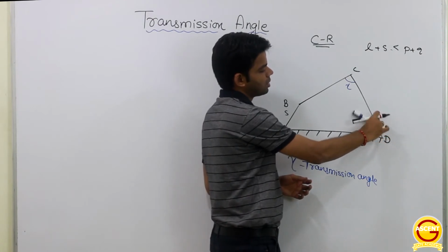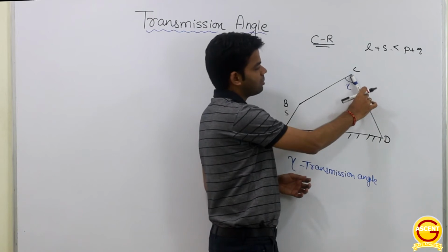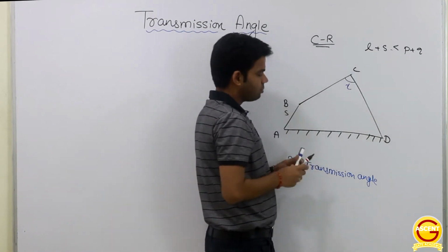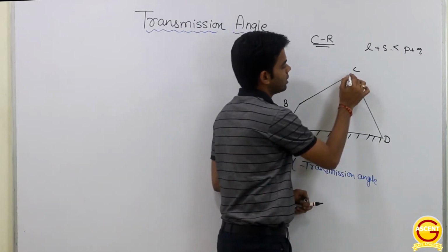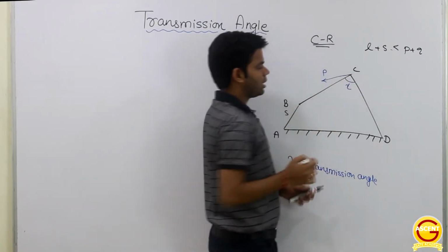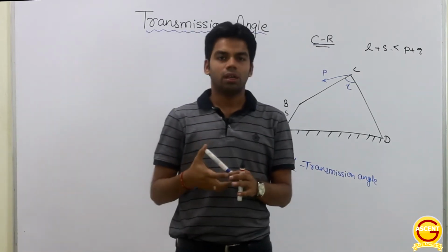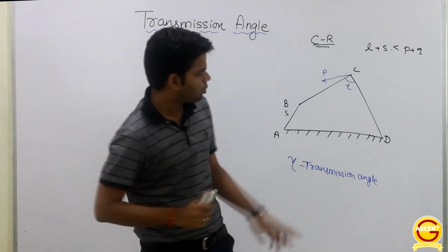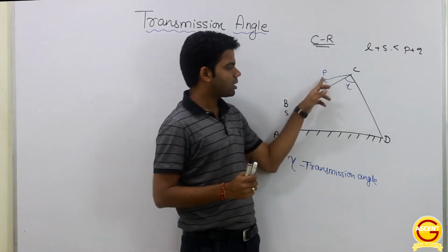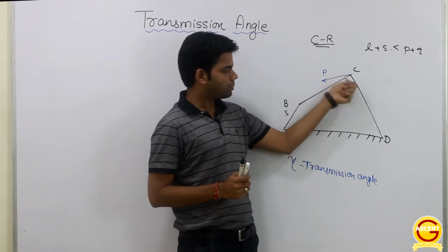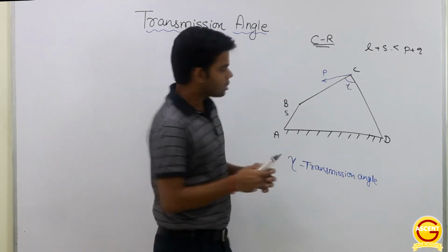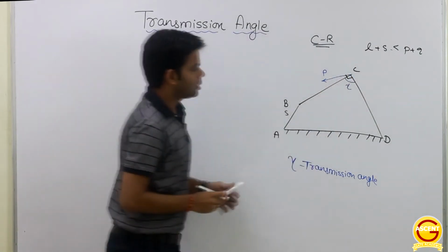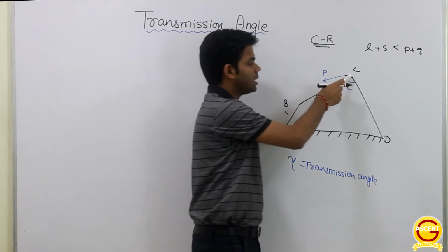Okay, ये इस तरीके से reciprocate हो रहा है. Getting this? That means अगर मैं यहाँ का point C का अगर मैं velocity vector बनाना चाहूँ, that velocity vector would be perpendicular to this link CD. Yes or no? Okay, in further lecture of velocity analysis we will understand this, क्यों इसके perpendicular होता है. But I think basic idea आपको होगी कि अगर link किसी point के about rotate कर रहा है तो उसका जो velocity vector रहेगा that would be perpendicular to that particular link. So this CP is actually perpendicular to CD. This is perpendicular. Getting this or not? Okay, तो velocity इसकी है along CP.